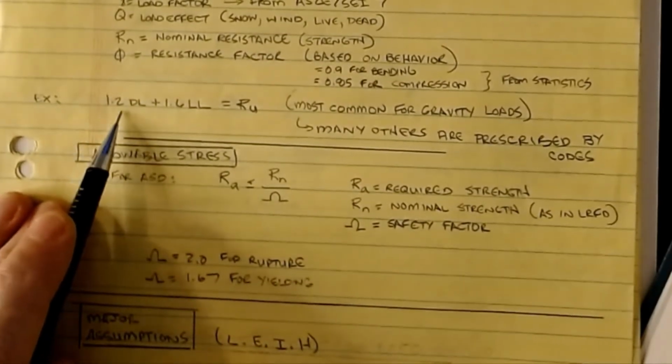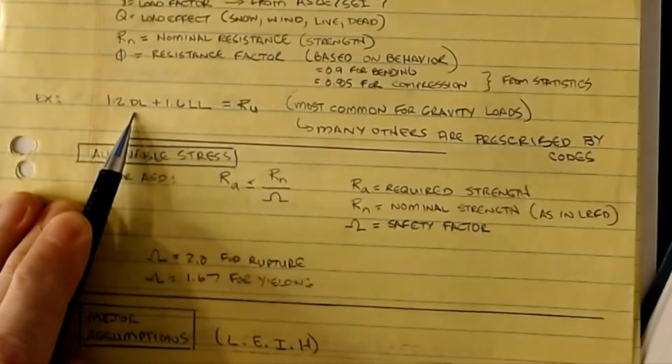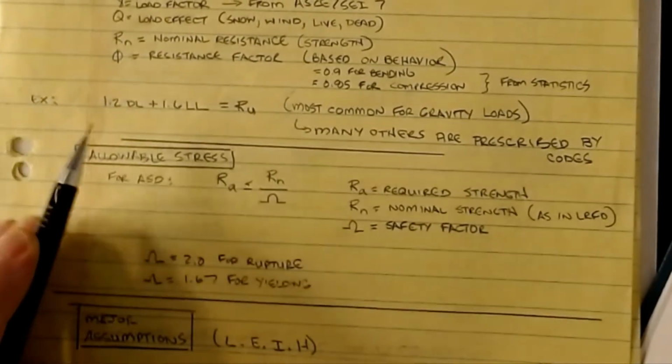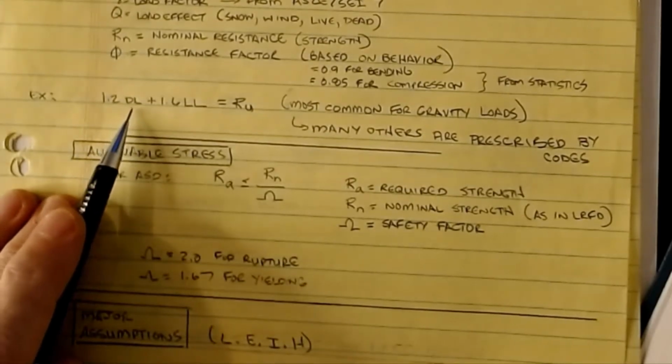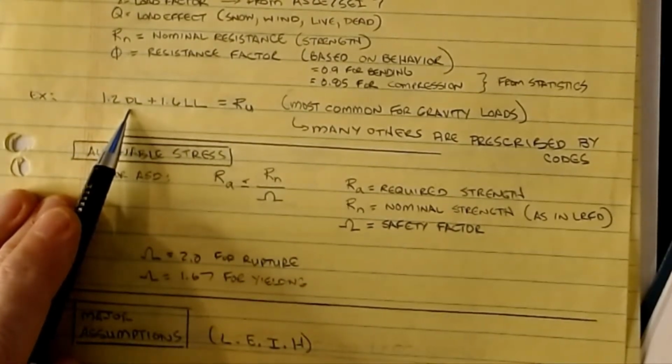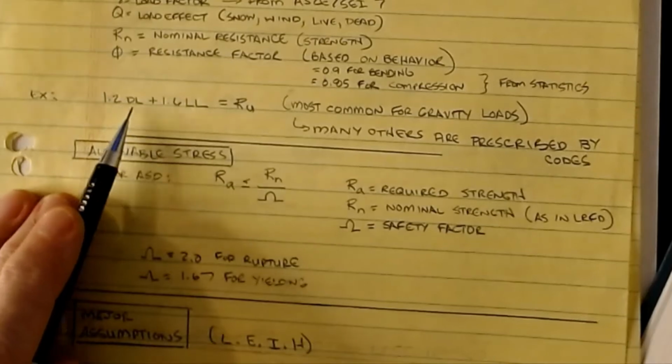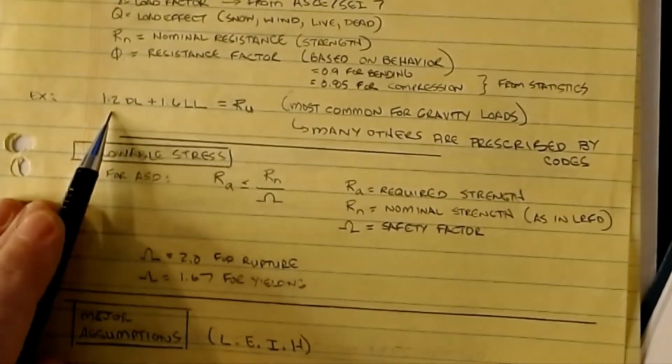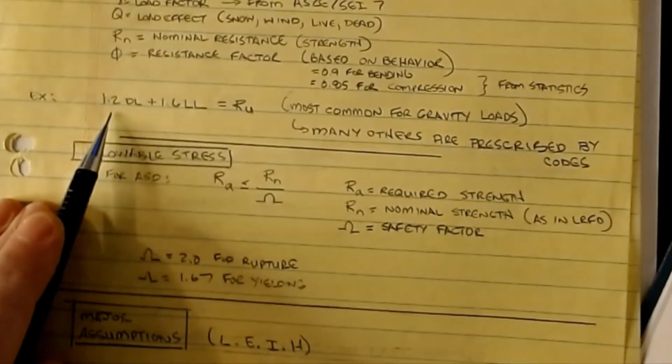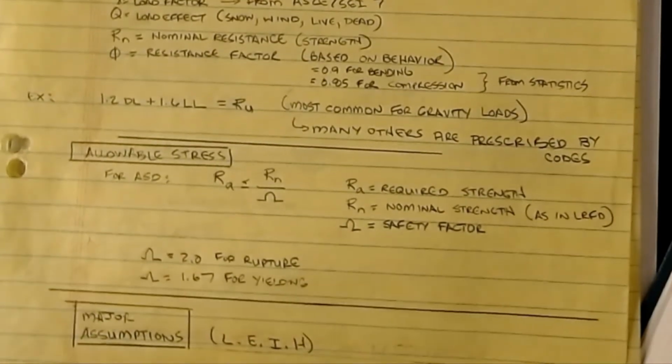The idea is that dead loads, I'm fairly confident in where they come from and that they're going to be there at all times. You know, things like self-weight or very heavy pieces of machinery that aren't moved on a regular basis. The weight of a concrete slab are all things that don't move or change frequently. So for that, I'm fairly confident in the positioning. I only have to worry about this 20% increase because my uncertainty level is a lot less.